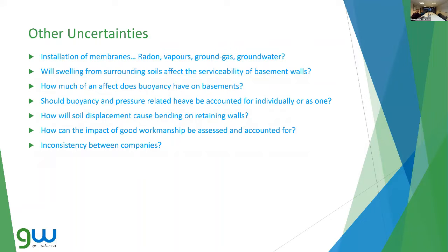So other uncertainties, Miltos briefly touched on the contamination aspect earlier. If the investigation is mainly for geotechnical and the client doesn't want to investigate contamination, then how do we know that the correct membrane has been installed? There could be ground gases, there could be vapours. And I think a lot of London boroughs, RBKC and Hammersmith and Fulham, are getting quite hot on vapours, and so yes, it's something definitely to look out for.